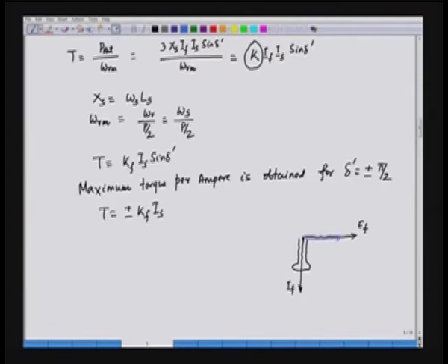This is Is; these are all phasor quantities. The current If is also a phasor, and then what about V? V can be found by adding the synchronous reactance drop, that is j Is Xs, to Ef. So, if we complete this vector triangle, we get the applied voltage, that is V.